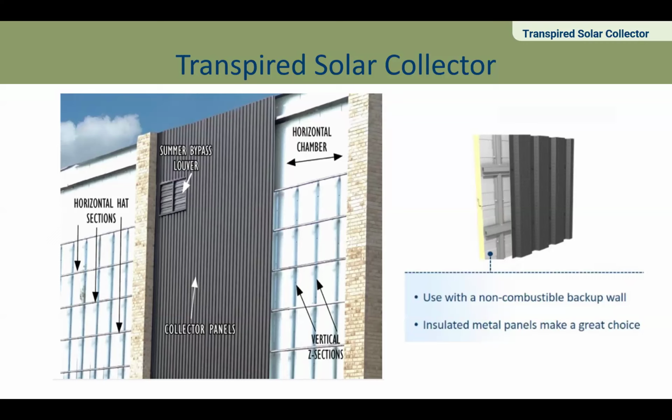We have seen systems where it's placed at the bottom or middle as well. But typically, you want it at the top because, as we all know, hot air rises. So the hottest air will be pulled up there. You want to leave a clear chamber there at the top to allow for maximum airflow as well. But the double lattice does a good job of providing that airflow so that you don't have these pockets that remain stuck in there.